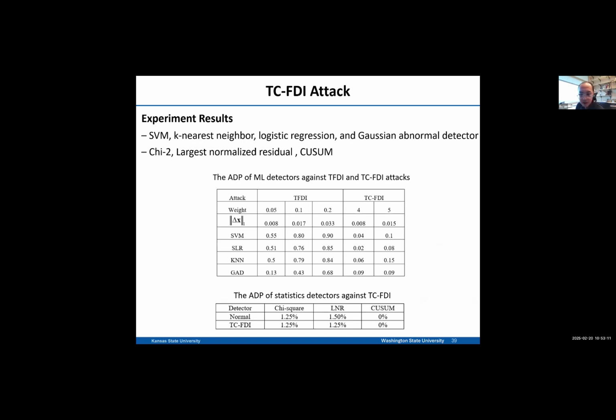Second, we found that machine learning detectors cannot detect the proposed attack with a large voltage injection but a low rank value. This low rank value reflects that the compromised measurements are consistent with the pattern of the normal measurements. Thus, the normal data and attack low rank data cannot be separated in the projected space and cannot be detected.